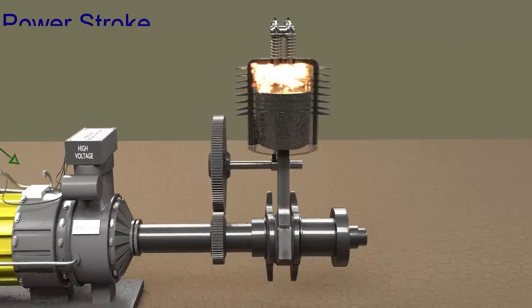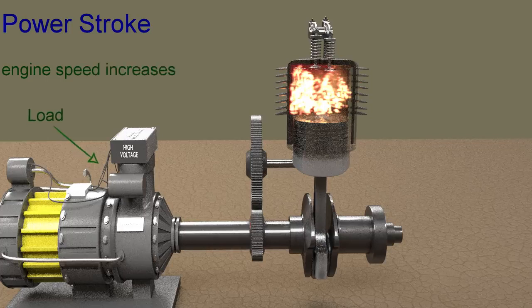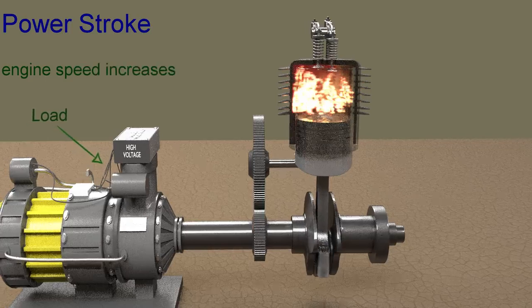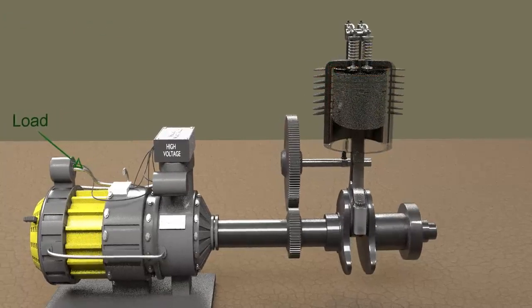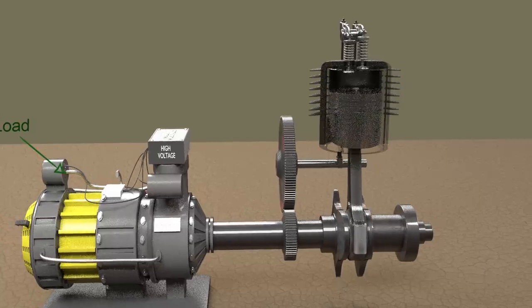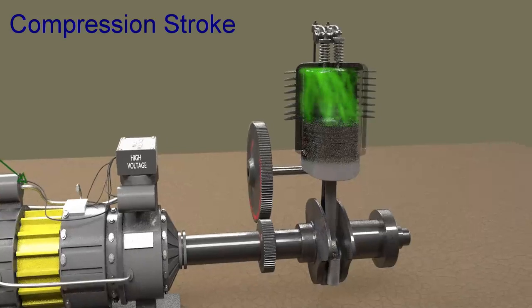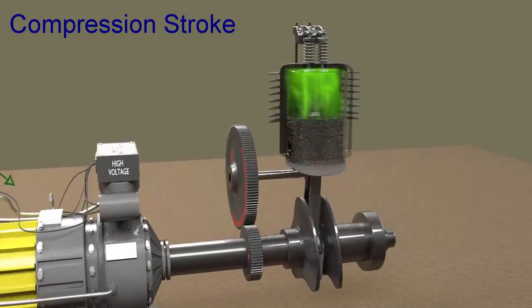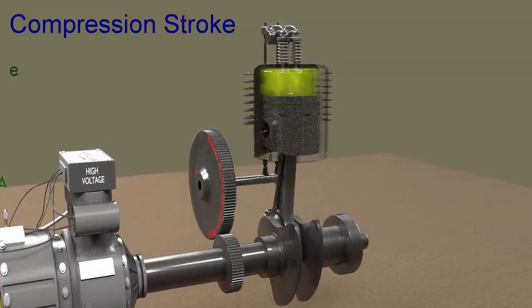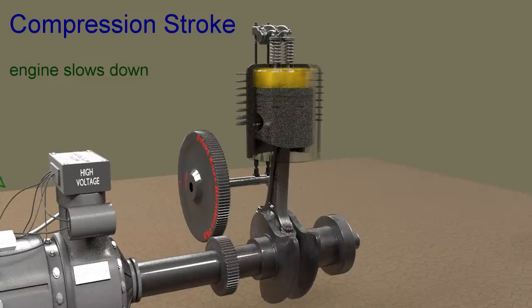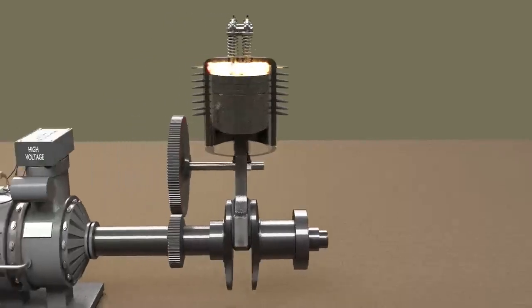During the power stroke, work developed by engine is much higher than required by the load, which causes engine to accelerate and speed of engine increases. Energy is required by engine in suction, compression and exhaust stroke. Especially during compression stroke, considerable amount of energy is required by engine to compress the charge to high pressure and temperature. This energy comes from the kinetic energy stored in moving parts attached to engine by slowing them down, and there is fluctuation of speed.